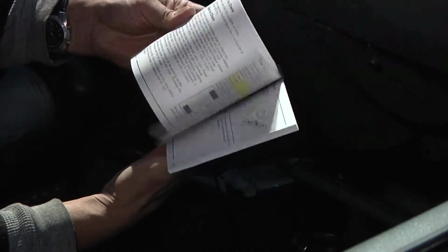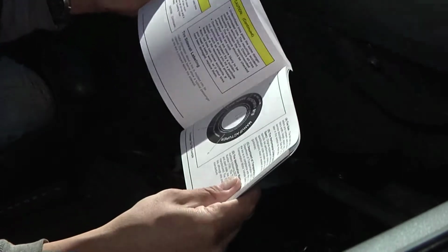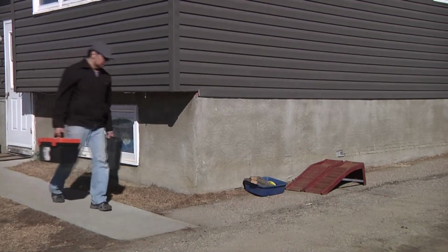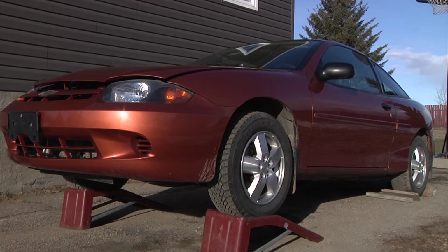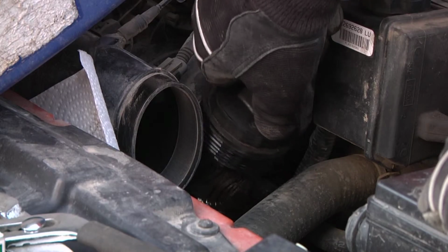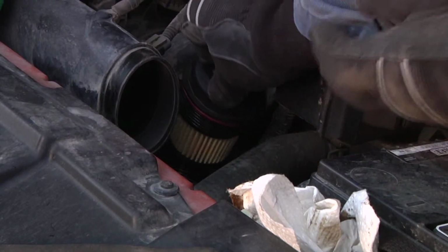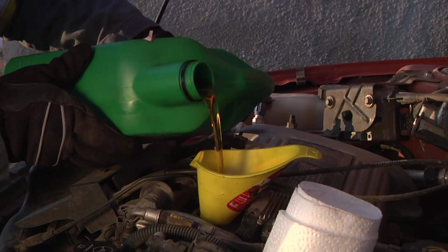To recap this episode, first we found what type of oil and oil filter we needed for the oil change. Then we gathered the supplies and tools we needed to conduct the oil change. We then found a suitable location and readied the vehicle for the oil change. Following that, we got underneath and drained the old oil and removed the old filter. Afterwards, we installed the new oil filter and added the new oil. Finally, we cleaned up our workspace and disposed of the old oil.